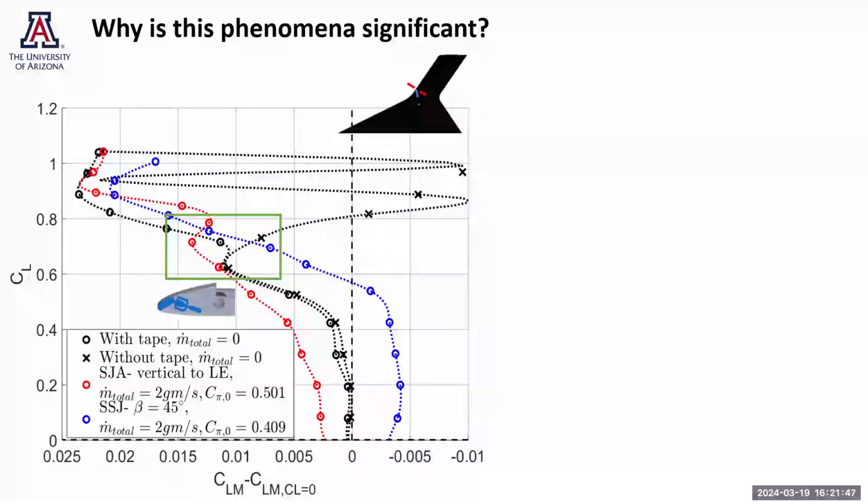So via these pitch behavior data points, we understand that there is something happening with this vortex liftoff that we are able to affect with the use of these actuators, but we don't know what we are doing. We are able to solve the problem without understanding what we are doing. As I mentioned earlier, at lower angles of attack the existence of the slot is irrelevant because the pitch is not affected by it.